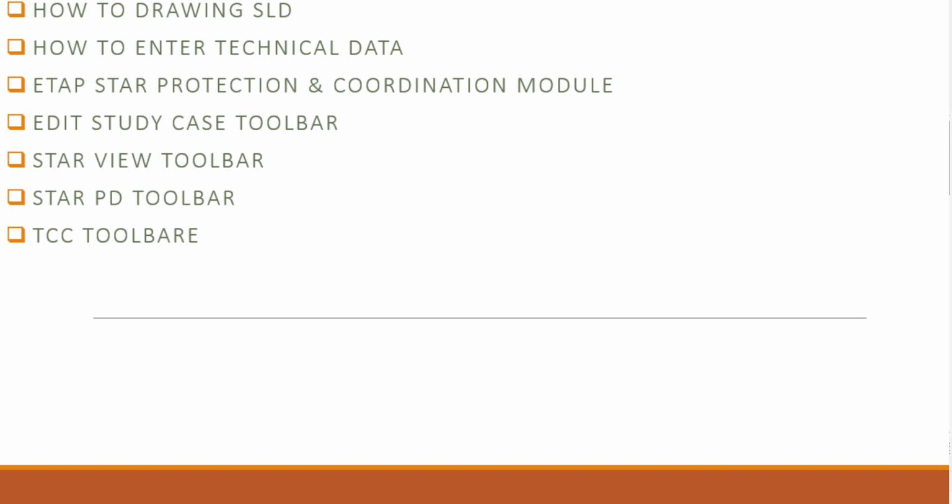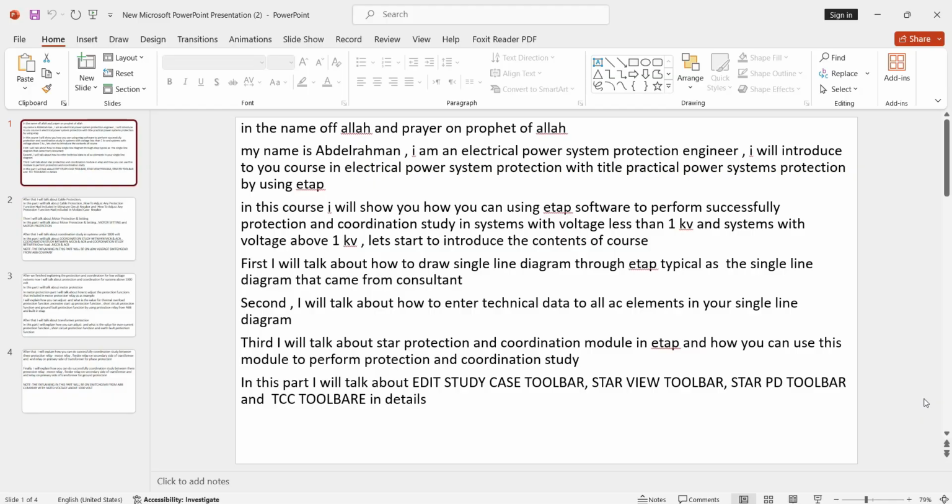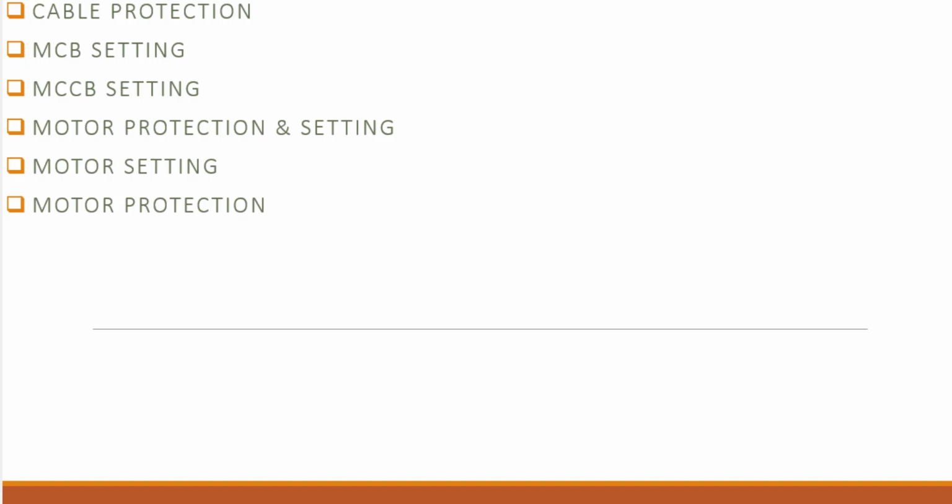In this part, I will talk about the edit study case toolbar, Star View toolbar, Star PD, PD means protective device toolbar, and TCC toolbar in details. TCC means time current curve. After that, I will talk about cable protection.